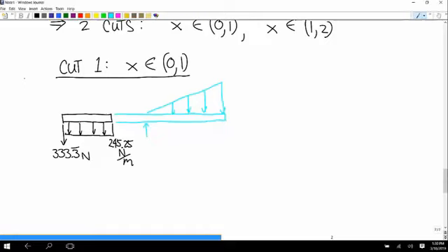Yeah, the whole key to calculating these internal loads is that we're trying to calculate the loads applied from the missing piece to the piece that we're choosing, treating this like a fixed point. And so we also have tension, the shear force, the bending moment, and the torque. The torque is just going to be 0 in this case because I didn't apply any external torques.